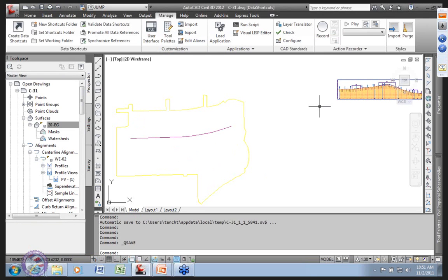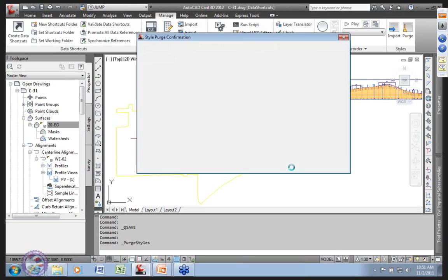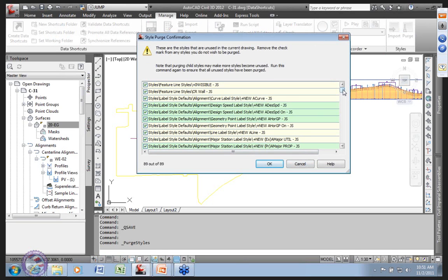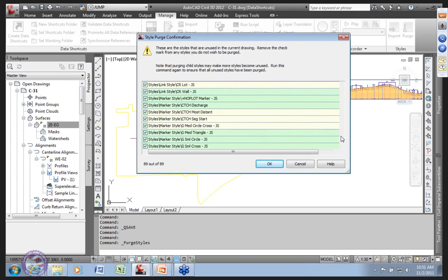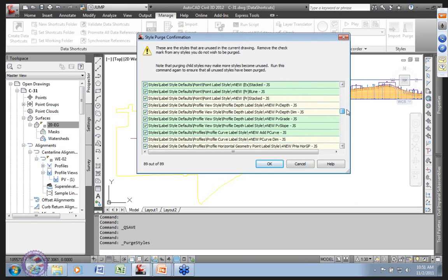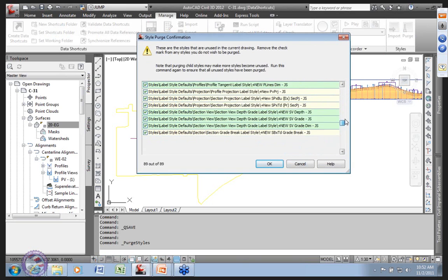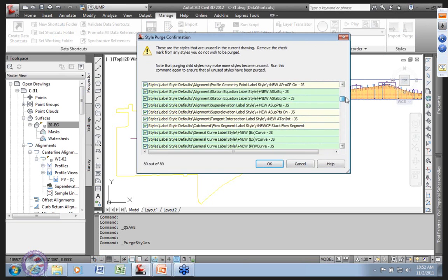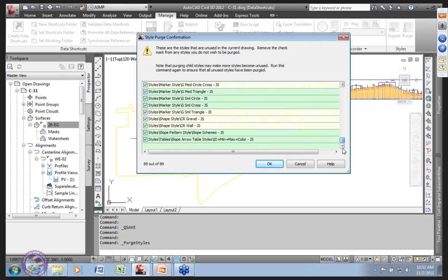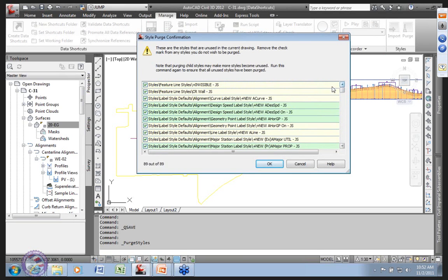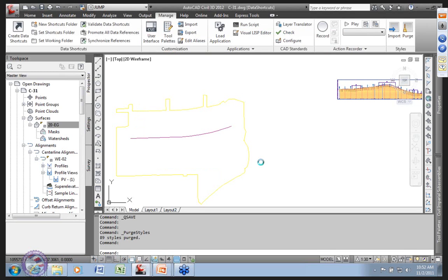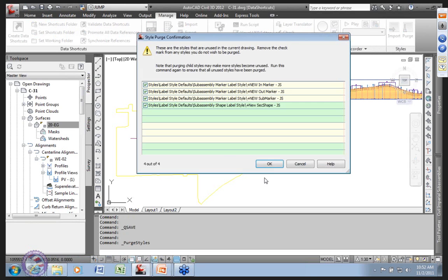And we know things because we've been using AutoCAD for years and years that no single purge works right away. And because in Civil 3D, and one of its burdens and pleasures is the fact that styles reference other styles. So when you do the first level of this, right, you get rid of some styles, and then because you got rid of those styles and they're not referenced anymore, other ones are available. So, hey, now we get rid of another 90. And, we're smart. We do a save. And, we purge one more time.